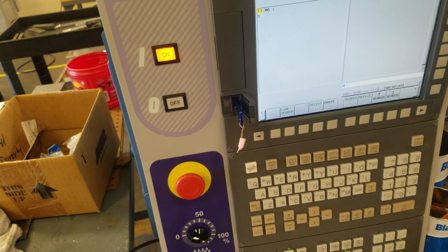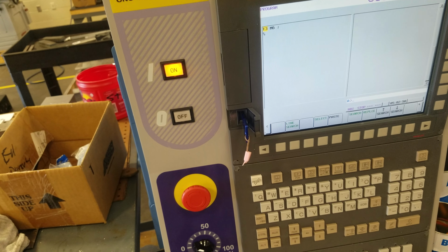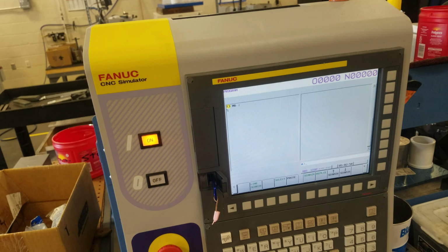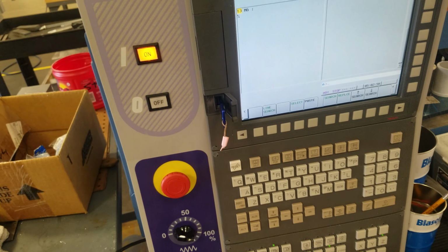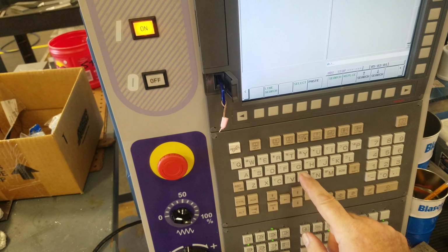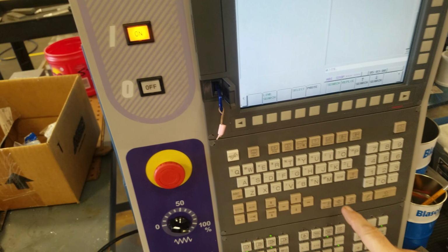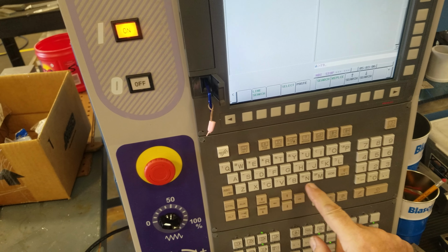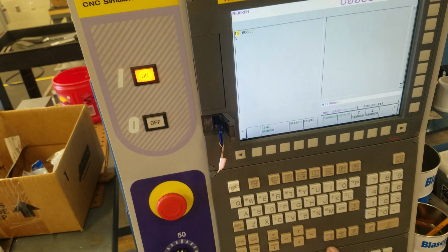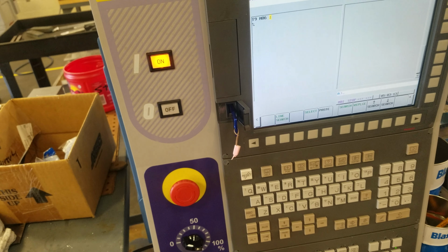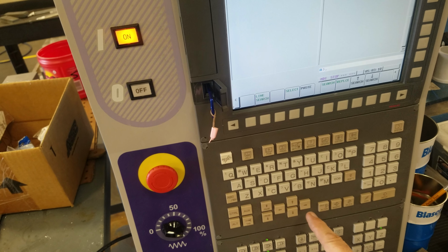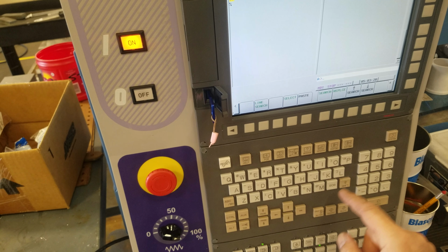Alright, once all the tools are loaded, we can do setting tool offsets and work offsets. So I would start with work offset first. If I had a drill chuck as tool 9, I'd have to call up tool 9. M06 end of block alter. Here we go. Cycle start. Next thing I have to do is set the RPM, because this will be no probe.